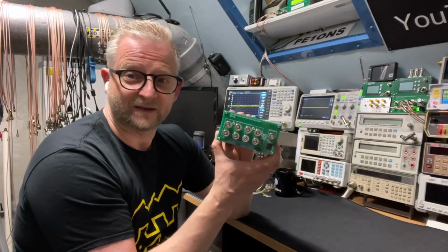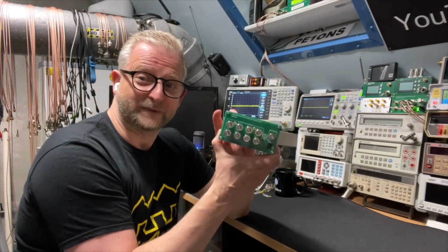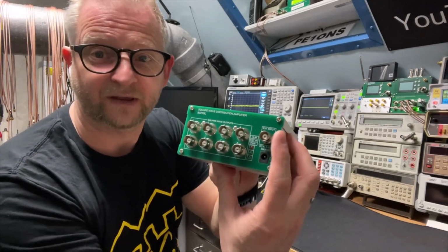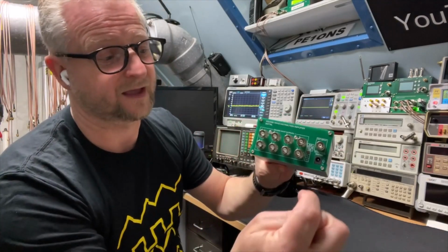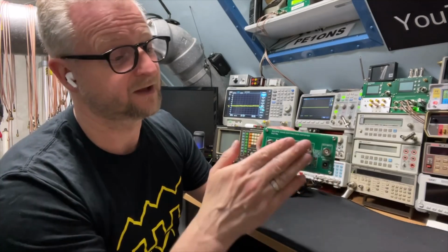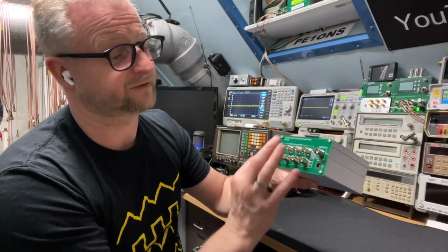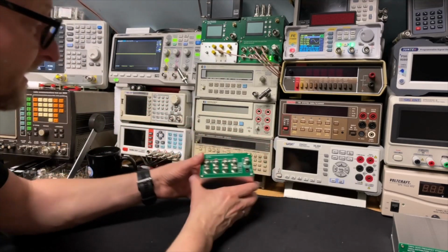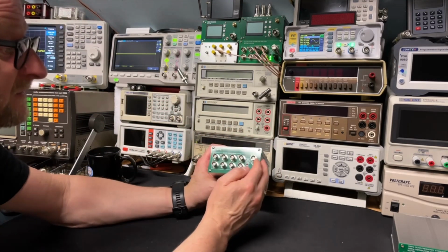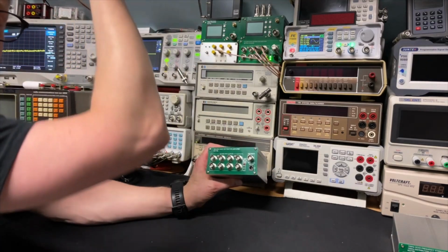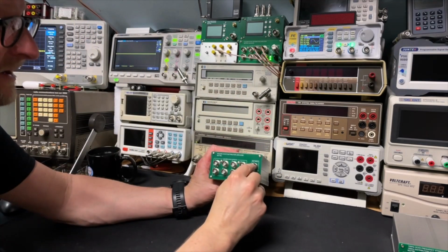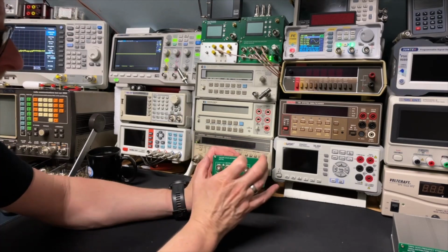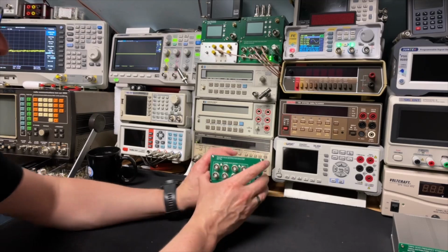And it actually does what it says. It's a square wave distribution amplifier. Here you have the input, and the signal that you put in will come out of these 8 outputs. The idea, when it is for lab reference, is that you connect it to the GPSDO. So the 10 megahertz from the GPSDO comes in here, and then you have 8 times your 10 megahertz out. Let's just do that.